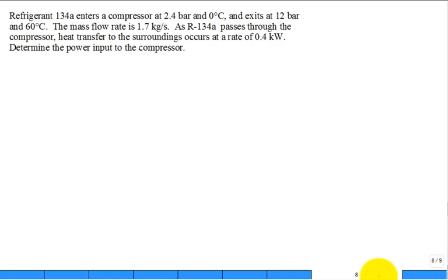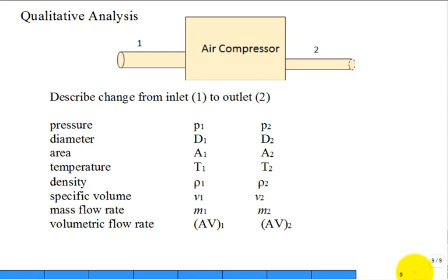Yes, sir. For your turbine, you said it was 3. They're all calculated the same way? Yeah. Different substances? Yeah, except for, say, the hydraulic turbine, it's liquid in, liquid out. So there's not a large expansion of the specific volume, but the huge change in pressure across it. So there are little nuances, but the same equations work. Yeah. All right. Let's take this approach.